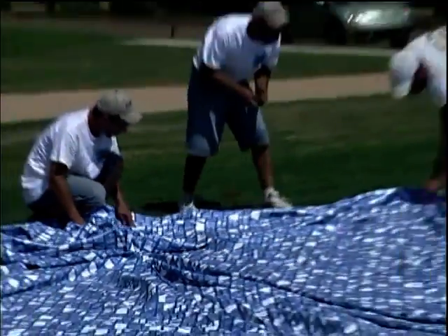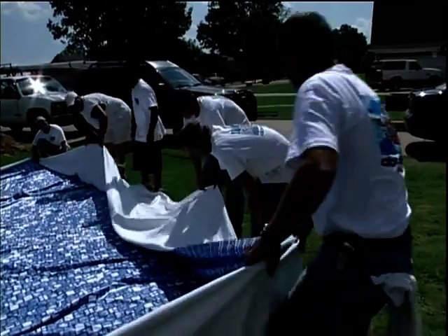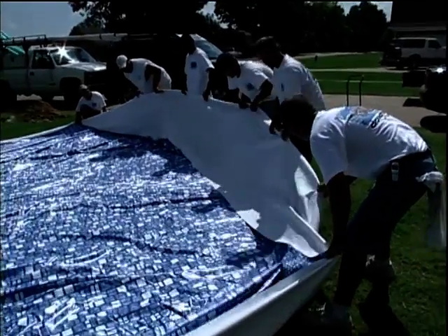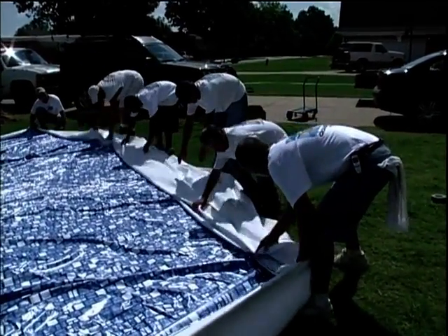At the base of the liner, mark the seams with a piece of duct tape to be able to see the point from a distance. Starting at one end, using the duct tape as a marker, drop the edge of the liner and pick up the bottom seams from underneath. Begin to fold the liner along the seams.